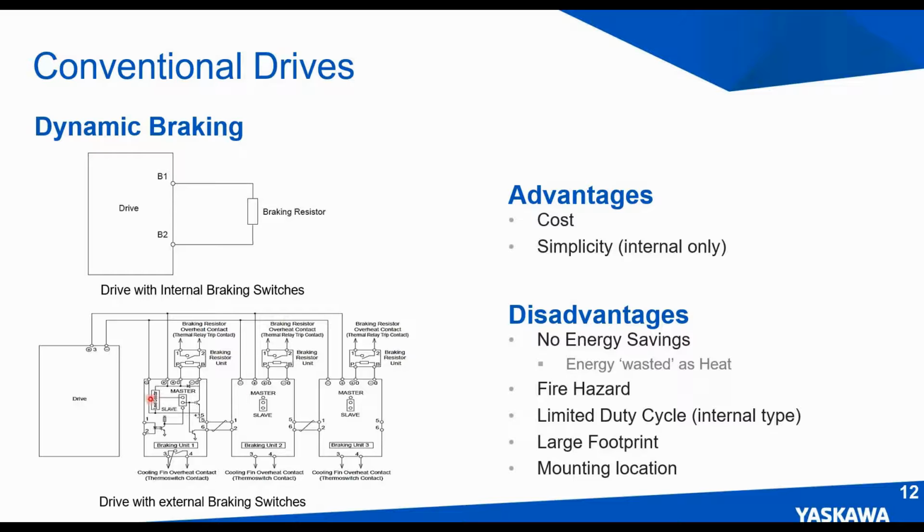The bottom image here shows you what a more complicated external braking package will look like. Bottom line is these options waste energy, plain and simple. They burn off extra energy as heat, kind of like a toaster. Additionally, the heating element presents a safety risk if combustible materials were to fall onto or nearby the hot resistor elements. Essentially, you're creating a fire risk.